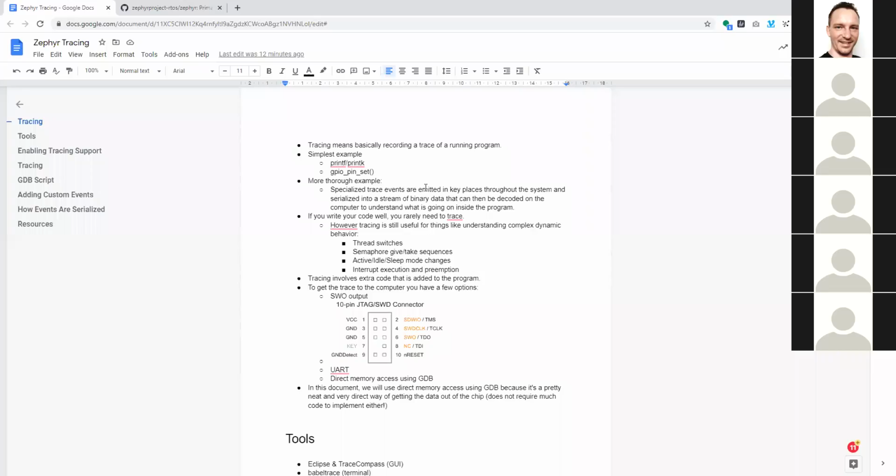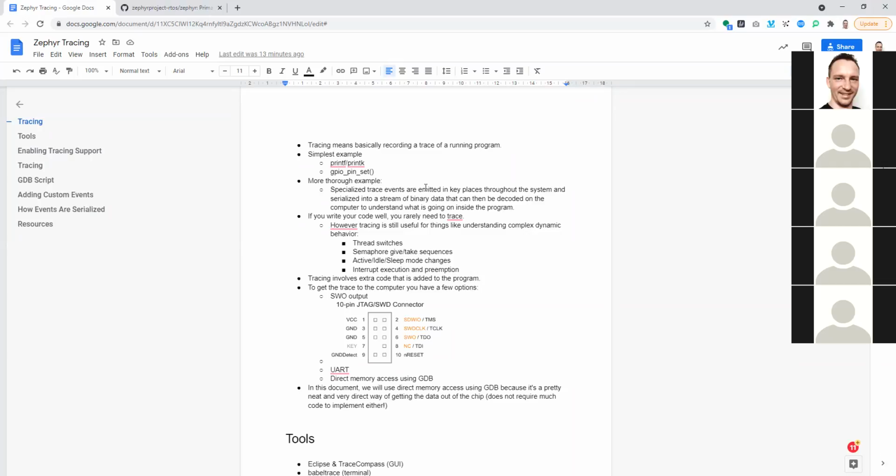By doing so, you can inspect the timing of the application and in what order things are happening. That can be useful in very fast applications where you have events arriving at a very high speed, like microseconds between events, in which case you simply can't afford to serialize those events and send them over to a debugging tool for inspection. So then you're kind of forced to use GPIO pins.